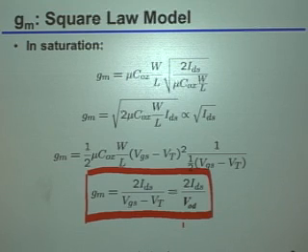Because if you're worried about getting more parasitics, that does also affect your bandwidth, basically the same thing, right? So you said more parasitics means that bandwidth will be reduced. That's basically what I'm getting at, that intrinsically the bandwidth you can get out of the device will go down as you decrease that overdrive. Yes? In terms of power. Okay, so what about the power? Okay, so there's two things that you said there. One was that if you reduce that overdrive, then indeed you'll get more GM for the same unit bias current. That's true. That's a good thing.